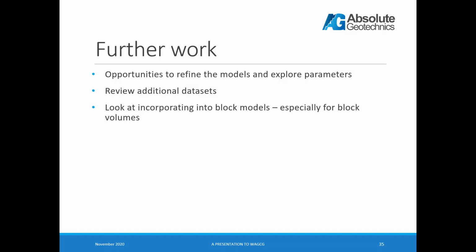So there are some fundamentals that make sense. I think there are some ways it could be used, and it could potentially be incorporated into block models, especially if you get relationships between how far you are from structural features like faults and fold hinges, and whether that has an effect on your RQD or your fracture frequency. There's no reason why you couldn't run those same algorithms on points in a block model. But also, in terms of strength, this may give you a different version of the truth, a different version of the block model, to test sensitivities or to inform you at the planning stage, or the earlier stage of projects.